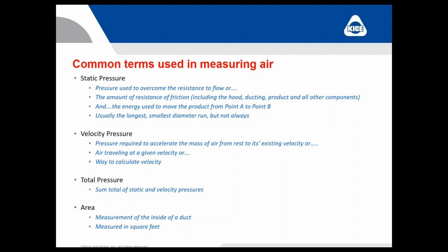And then the other thing that's important is to know the area on the inside of the duct, and it's measured in square feet. So you have to do a little math, come up with a diameter of the inside of the duct. You can cheat and take the OD, but you give up a little bit if you don't use the ID, and then you convert that to square feet.